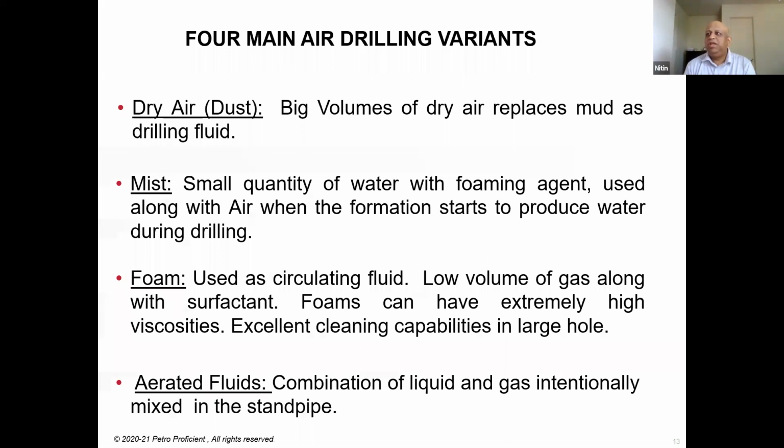So what is air drilling? In air drilling, just big volumes of dry air are used to replace the mud system. That's it. You just use air. This may sound a little unusual for those who may not have been in operation, but I have been there, and it is just called dust drilling. Why is it called dust drilling? Because the formation cuttings that you're drilling come out in the form of dust. You're basically just blowing dust out of the well. So that's why it is called dust drilling.